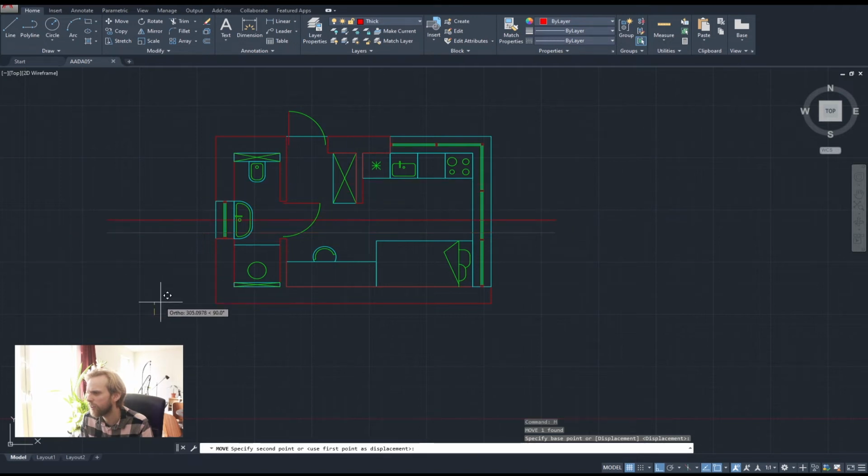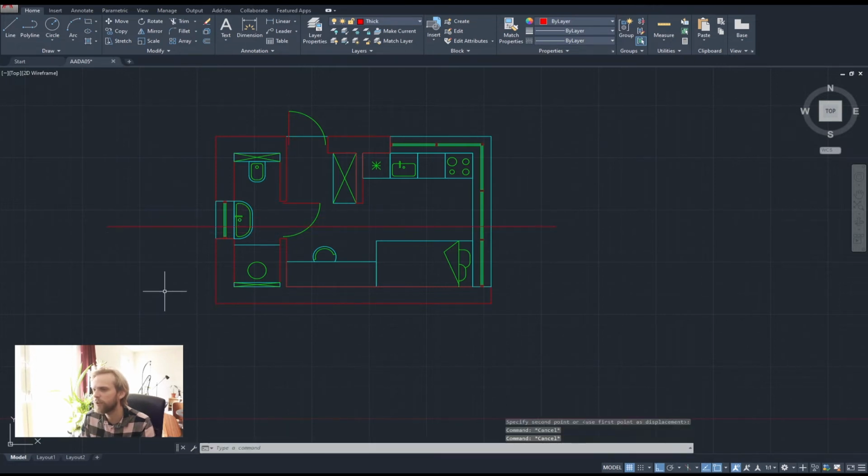So my thoughts are, and usually you don't want to cut through the furniture. You either show the furniture in the projection of the cut, or you don't, right? But you don't cut through the furniture. In this case, we are going to be cutting through the sink, but that is fine. If you are cutting through furniture, you're not hatching it in, so you're not filling in the cut. That is important to note. You're just showing it as if it's in the projection.